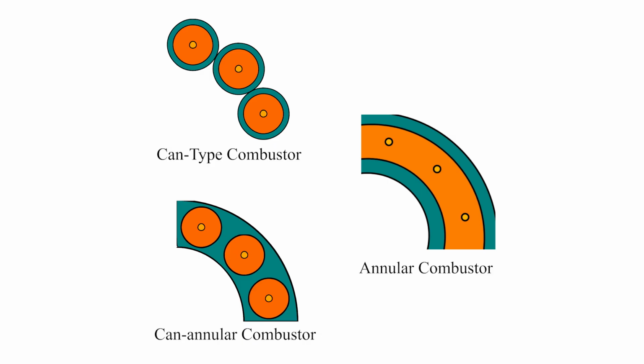This is achieved by injecting additional fuel into the jet pipe downstream of, that is, after, the turbine and combusting it. The advantage of afterburning is significantly increased thrust. The disadvantage is its very high fuel consumption and inefficiency, though this is often regarded as acceptable for the short periods during which it is usually used.